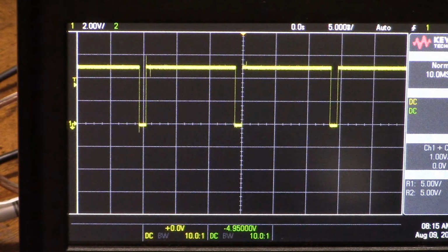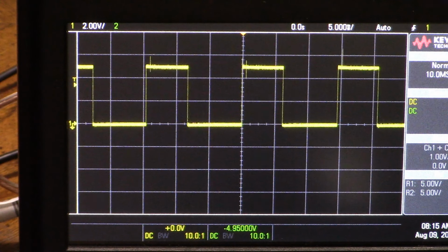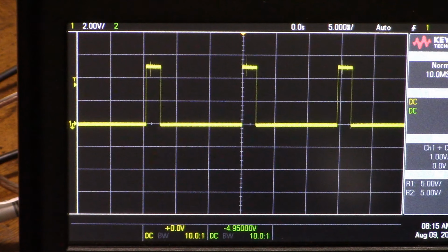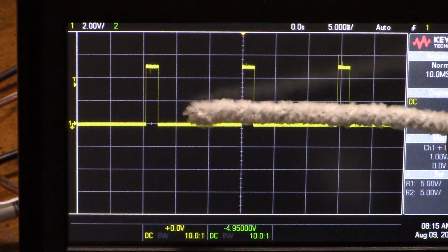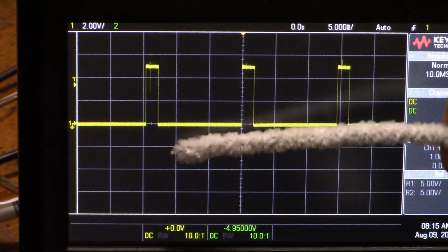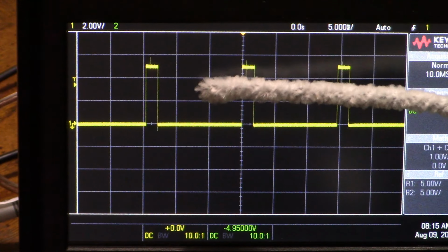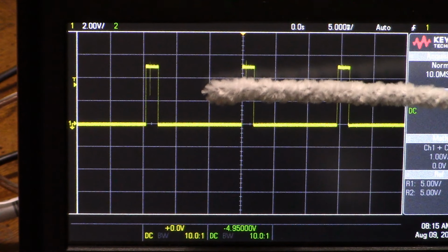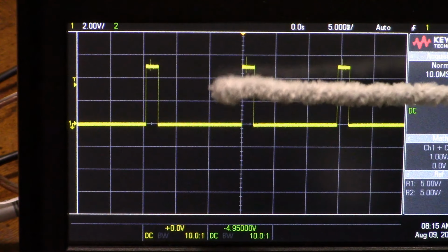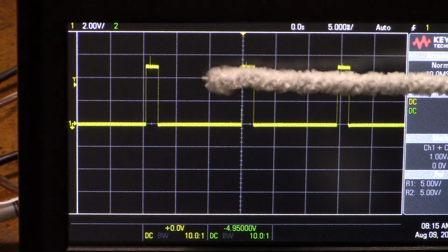I'm going to turn it the other way at a steady rate. So it goes down very fast and then it slows way down. It's not linear because the charging of the capacitor is not linear. You set a voltage, and the timer turns off when the capacitor charges to that voltage. The capacitor charges more slowly. The higher the voltage is, the closer it is, the more charged. The more charged it is, the slower it continues charging.